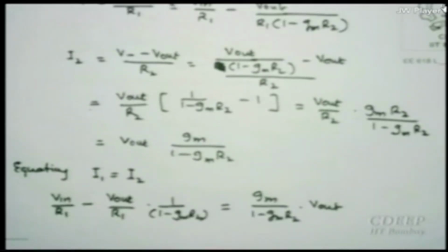Collect the term for Vout and collect the term for Vin and get a ratio of Vout by Vin. Note down what I have written. Because in a negative feedback system, the output V0 is out of phase with that, and therefore if it doesn't come as minus R2 by R1, you will start asking me where the minus sign came from. Now I want to bring this, and that's why I assumed the same direction as an op-amp uses.